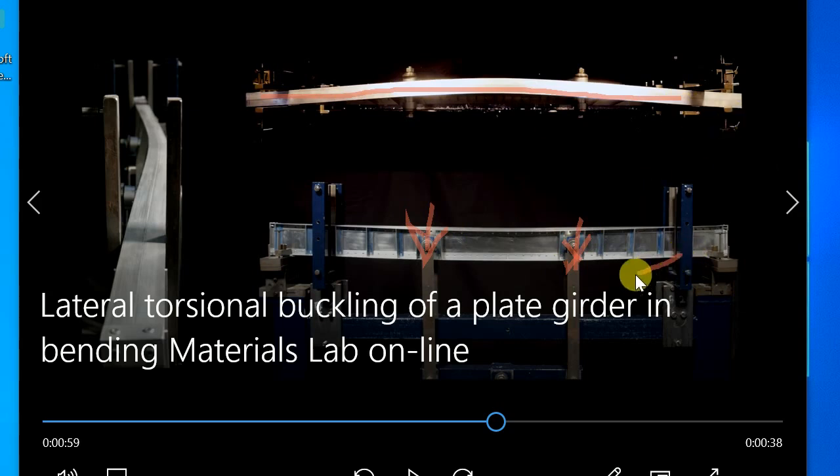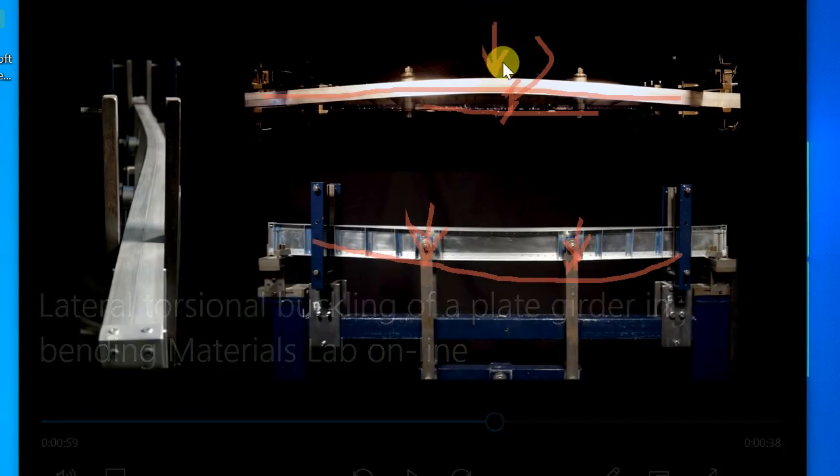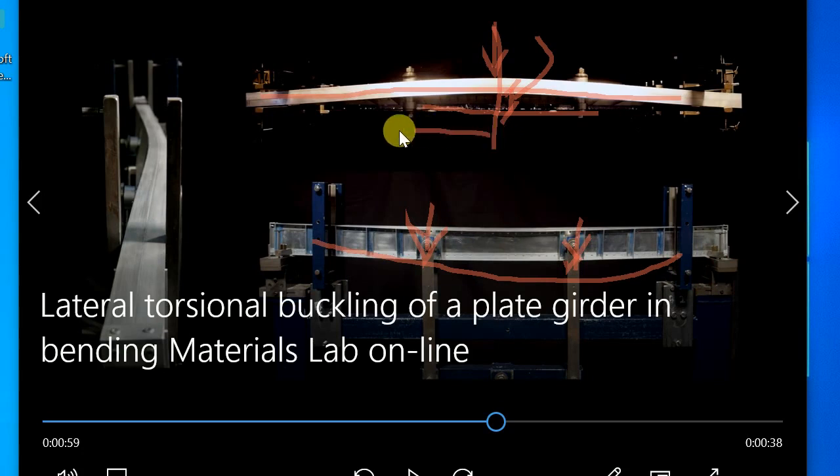Bending is basically the beam deflecting in the vertical direction, but this is in the horizontal direction. Clear? You see the deflection of the beam from its initial axis in the horizontal direction. This is your lateral torsional buckling, and the beam twists in this direction and bends in this direction. To prevent this, we need to apply a force overhead to bring the beam back into its original position. So for that, we provide lateral support to the beam, and that basically divides the beam into two separate portions.